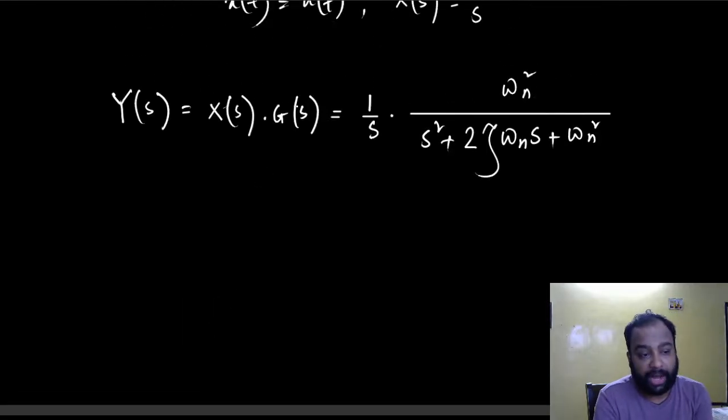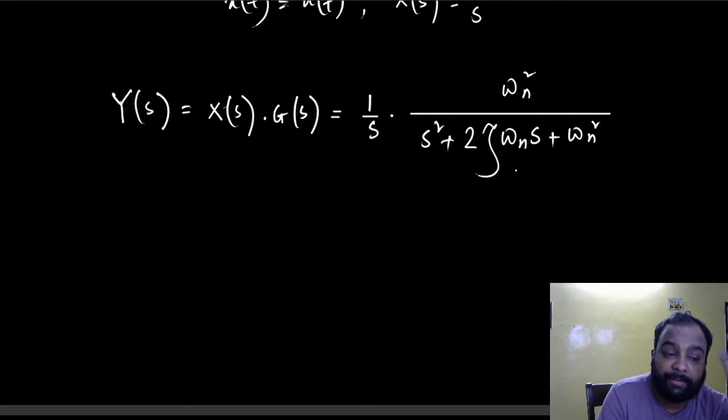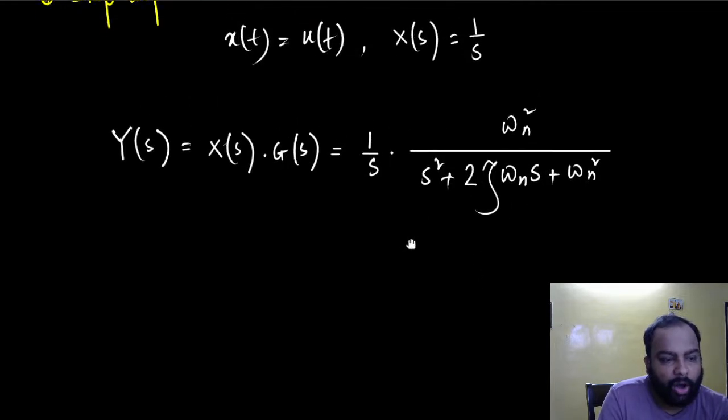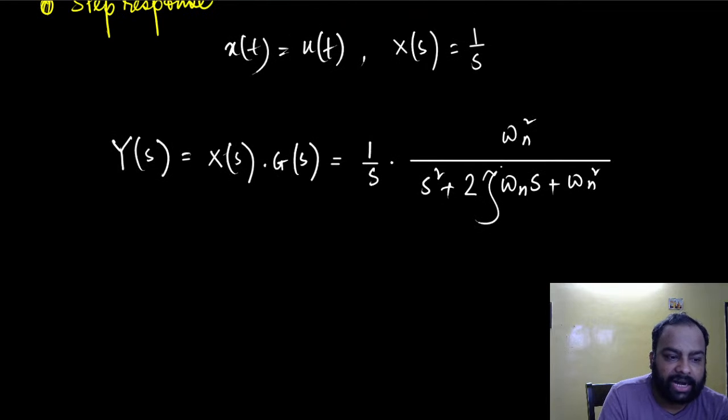Now we have to figure out the inverse Laplace transform of this complicated thing. All right. But you have to understand that figuring out the inverse Laplace transform won't be easy if we don't impose certain conditions on zeta, right? Now, for our purpose, zeta is going to be only positive, because if you recall in our earlier discussion, this term came from something like this, zeta omega n.